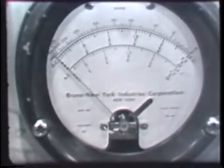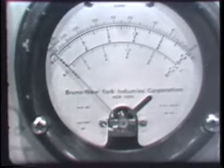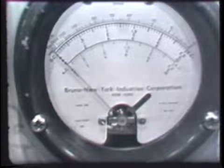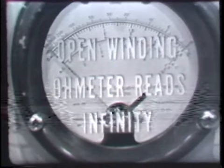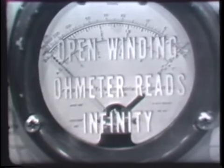If we take a look at the meter now, we'll see that it reads infinity. Well, since a PSM6 always reads infinity for an open, this then indicates that the 150 turn winding, the one I'm now measuring, must be the open winding.